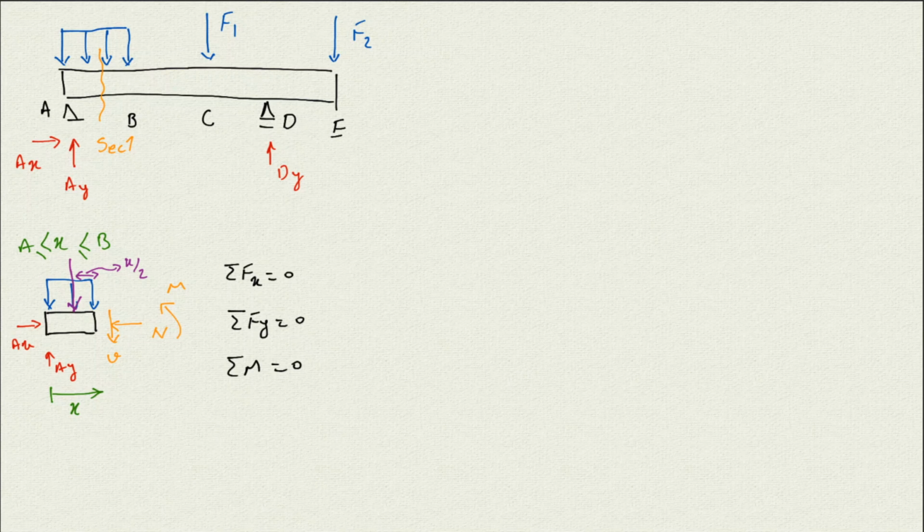So if I want to go to the next section, I go down with this distributed load. The next one is between the distributed load and the next force. So between these two sets of force, that's where we're going to have it. Again, if we have a distributed load, we need to have a section between every two sets of load we have. So it's going to be section 2.